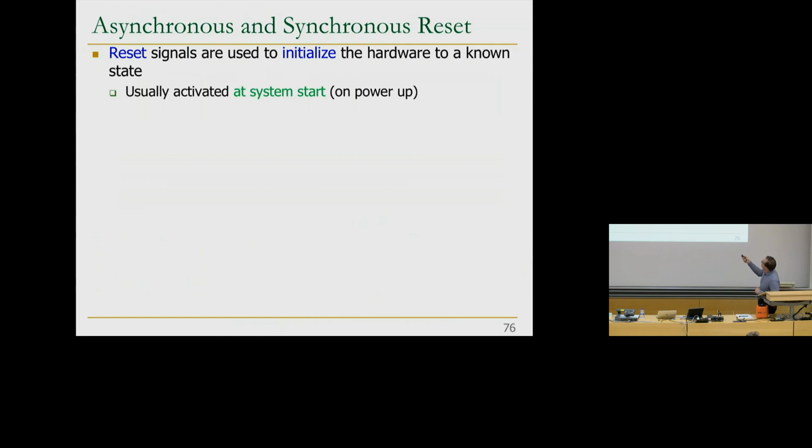We use this to initialize the hardware to a known state, usually activated at the system start. When you turn on your computer, the first thing that happens is that all of the things get reset to whatever values they need to capture. 0 usually, but it doesn't have to be 0 either. Okay, so there are two kinds of reset. One is asynchronous, the other synchronous. Usually, remember, the clock is the synchronizer. That's the great synchronizer. It synchronizes everything.